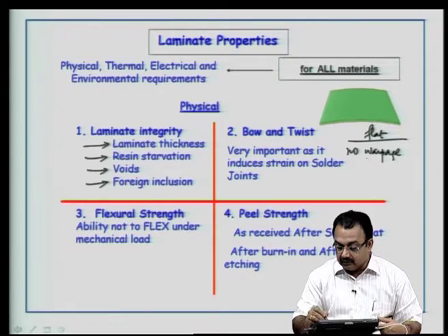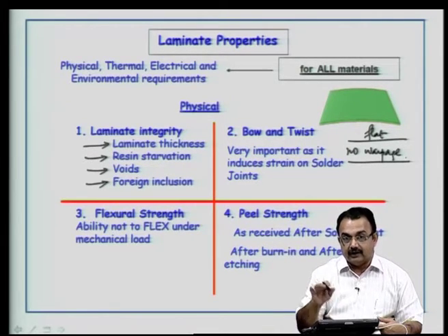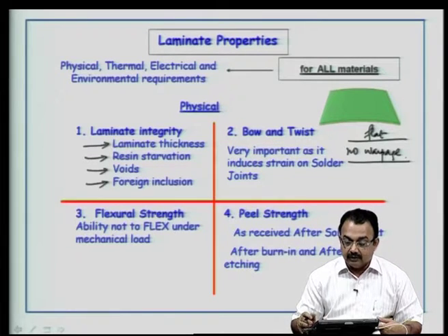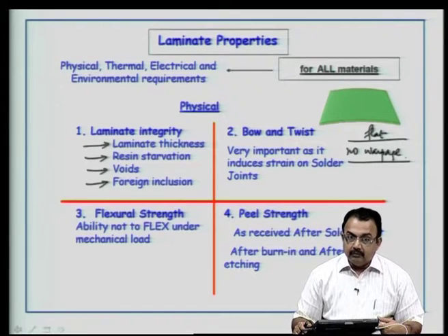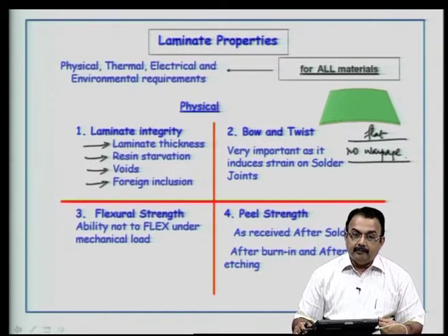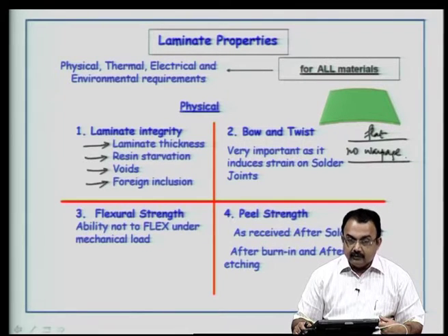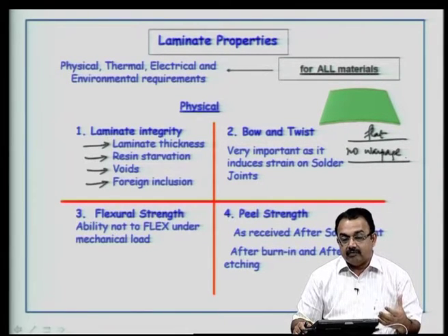So, the storage also becomes very important. How you store your laminate? It should be stored flat, okay, horizontally. It should not be kept standing. Now, the bow and twist property is important because it also indicates how the manufacturing has taken place in terms